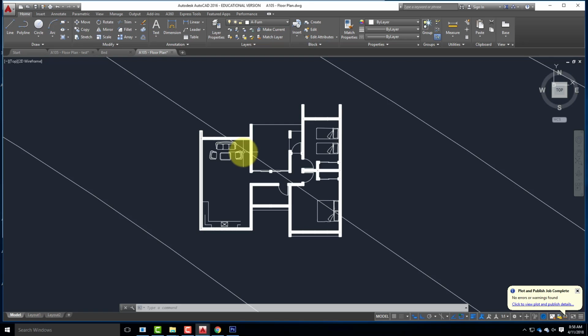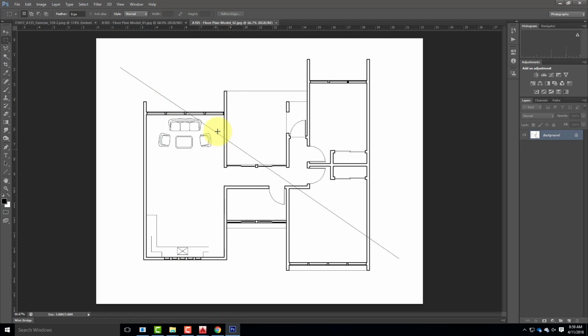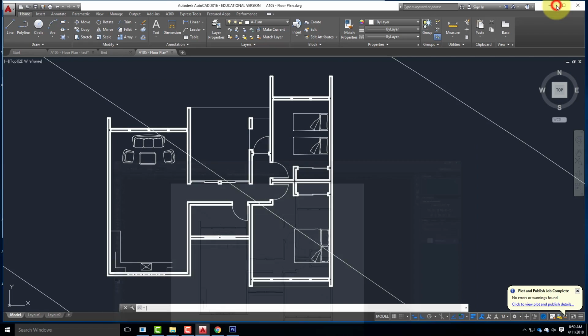And in AutoCAD, sometimes you want to fill in a region with a particular cross hatch or set of lines that are all parallel to each other or a certain pattern. The simplest, easiest hatch is just a solid hatch. So let's say, for example, that I really wanted this to show up a little bit darker, even than the drawing here, and I wanted to fill in all of the walls as black. I could do that using what's called a hatch.